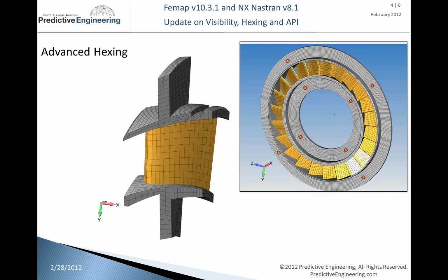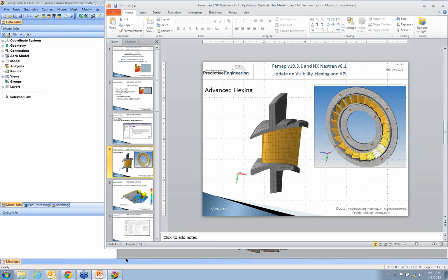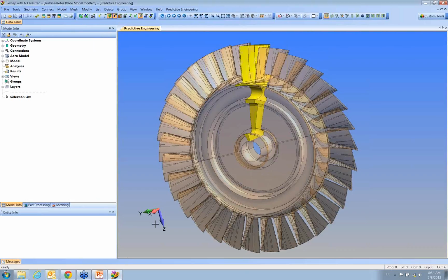And let's talk about Hex Machine. This shows one component. It's an air inlet vane nozzle vane guide, and it's all hex meshed. And there's another part. There's a turbine rotor that was required to be hex meshed also. And I'm going to show the setup for that, the first part, because it's not exactly intuitive, and it's something that I had to get some assistance with figuring out.